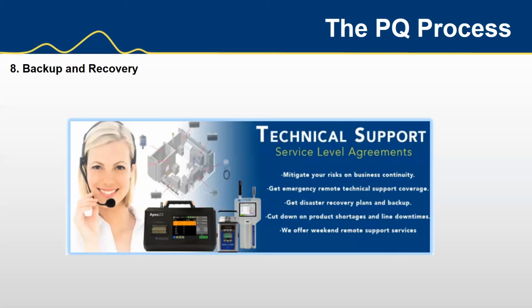Can the data be automatically uploaded to a secure 21 CFR Part 11 compliant database, or is it a manual upload? What happens when your network goes down? There should be redundancy built in. For example, is the EMS software or external vacuum used to pull samples through remote particle counters? Are they on redundant systems? Are they on the facility UPS grid? What do you do in the event of EMS server failure? Is there an automatic redundant EMS server running in the background waiting to take over? Is the system set up on a virtual server? All these things you need to consider and test. Test them fully in the PQ. I can't stress enough how important the PQ is.